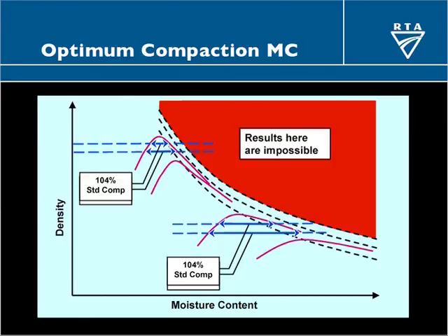And even if we allow for the higher target value, we've still got a much higher range. And again, this is consistent with what most people have seen in practice, that clay cohesive materials are a lot easier to get the compaction in than granular materials like pavements.